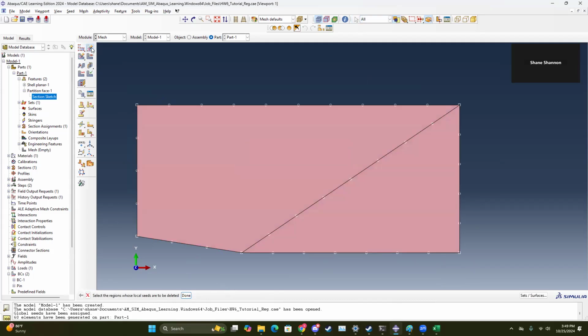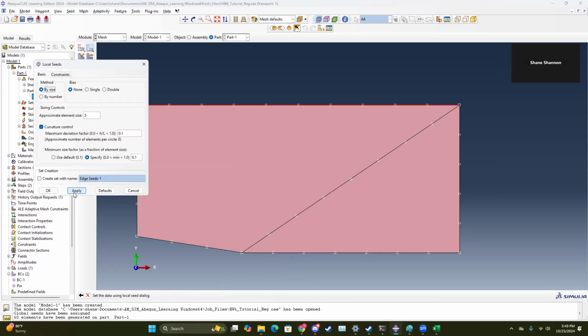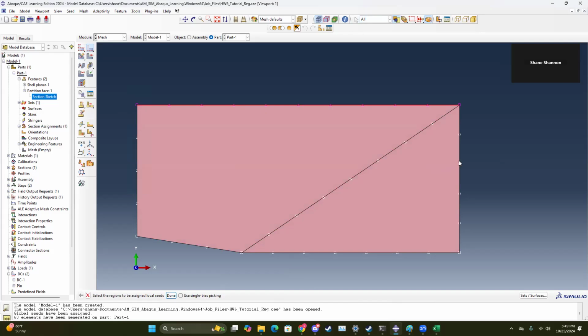Oh, okay. Go. So no edges. Cool. So when seeding, I like to do it edge by edge, so you can do it case by case rather than the whole thing. So these areas that are nice and far away, do larger sizes in general.